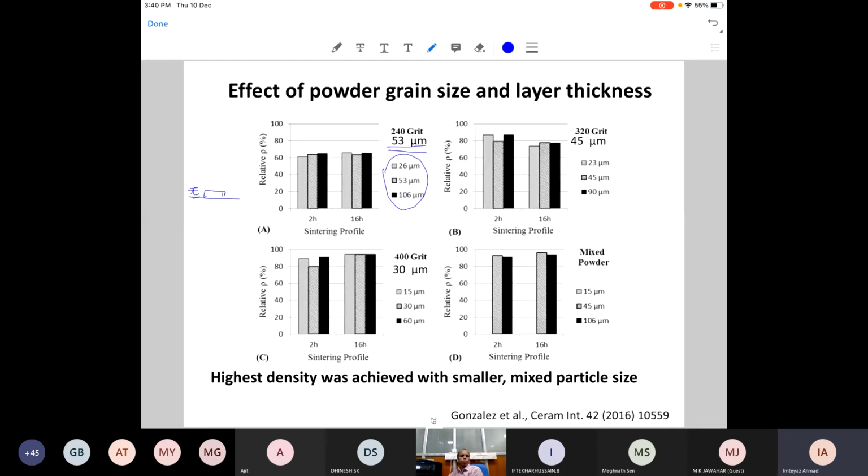So in order to lower the melting point, sometimes you add some additives or other compounds which react and form some kind of eutectic or low melting compound with the parent material, and give you a flowing liquid or a fusing liquid or a mushy zone somewhere between the grains or between the particles, which allows the particles to resettle and pack better. And it also acts as a bond for the whole thing to become dense.